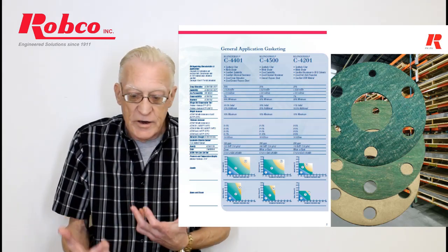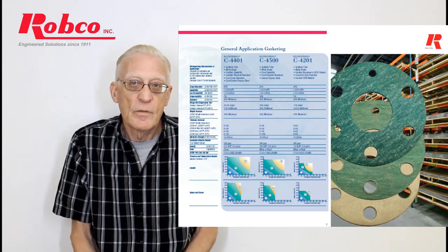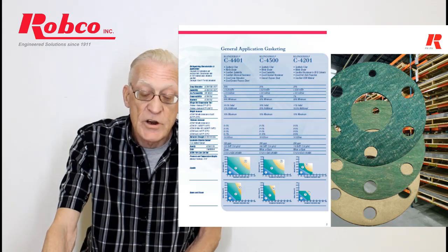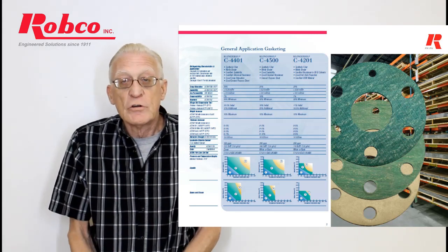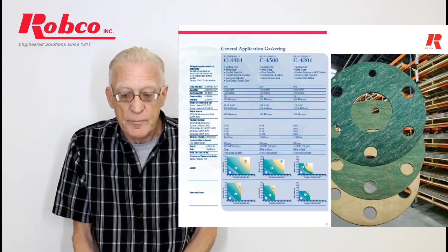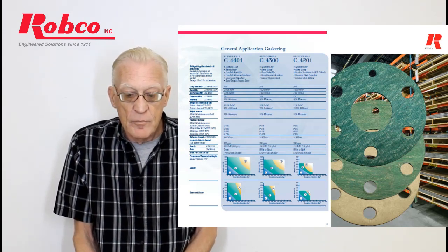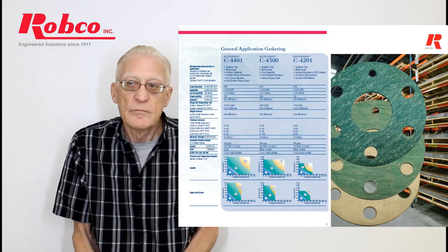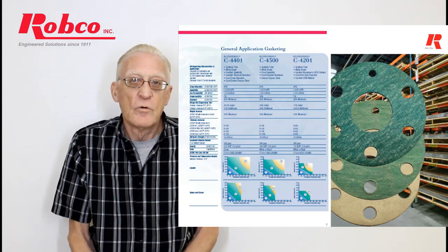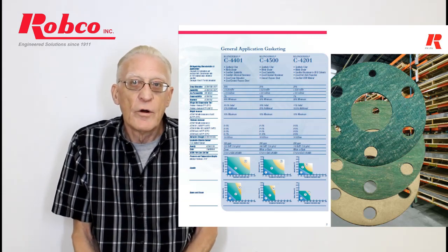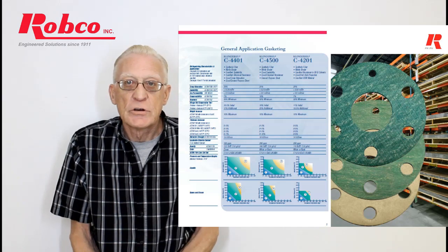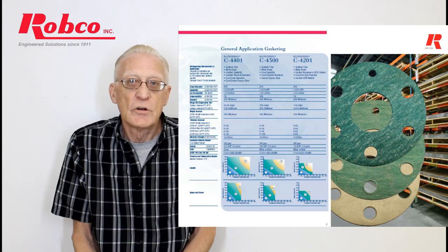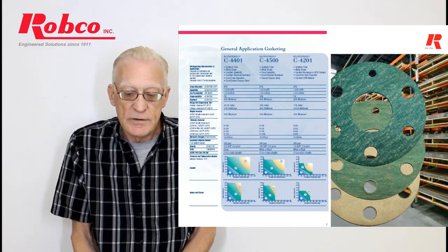It takes more pressure and more temperature. You can see, that's what we're here to talk about, is what will it do in your flanged application. The original green, I stole this from the Klinger website, going back to hot compression. So you put that gasket in, install it right, walk away, the equipment's running, the boiler, if you want to call it, high temperature, high pressure. You really want to know what's going on with that gasket. Is it going to hold up? So you take a look at the hot compression test.